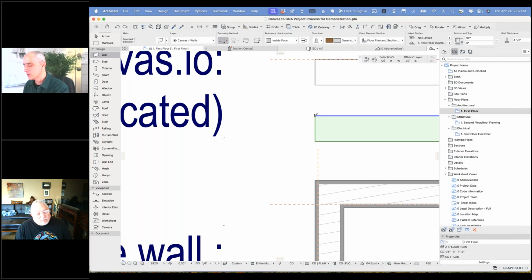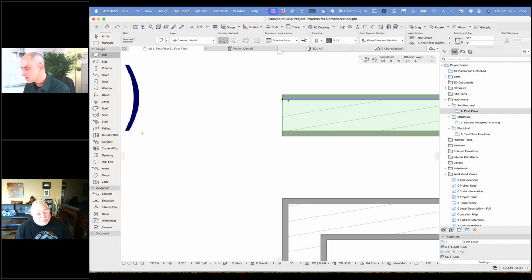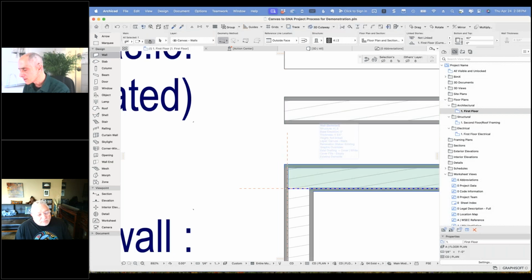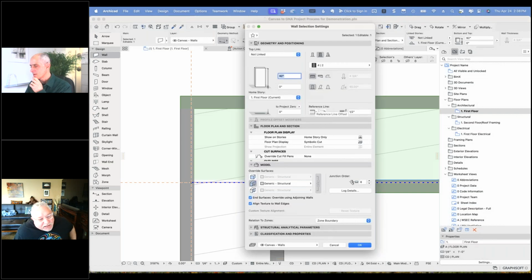And when I redo the two things, now it is at the face of the... Well, actually, it's not quite. Why do you have this inset? You don't have it set accurately here. Were you aware of that? You can check and see if that's 5/8 gypsum wallboard or 1/2 inch, because it might be taking a 5/8. Right, okay, so it's set to be inset 1/2 inch manually.